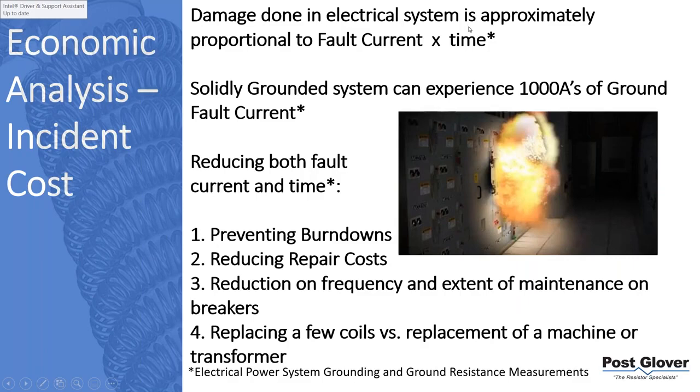So I went to a reference book to dig this up. Essentially, if you look at high resistance ground versus solid ground, we're talking about a very low current for a longer period of time, or a very high current for a short period of time. So you would think that maybe they're almost the same, which is intuitively correct, but not true.